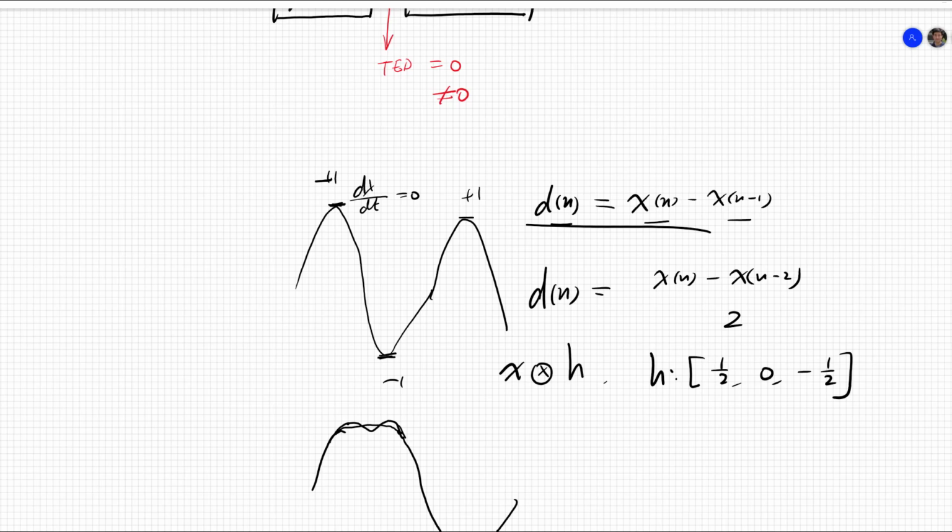For a practical random symbol stream, the maximum likelihood timing error detector output could be very noisy, and this noise is called the self-noise. When we encounter a random symbol sequence, a zero-crossing timing error detector can be very useful.